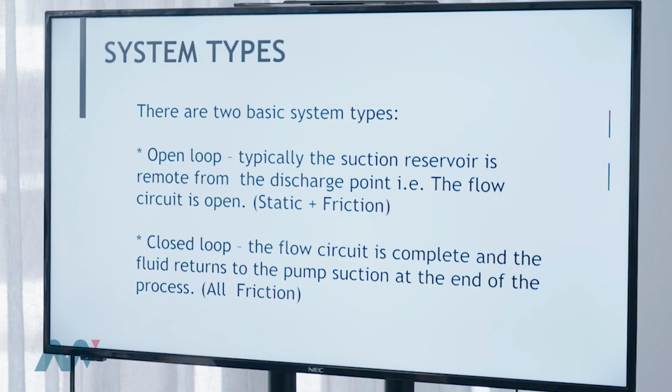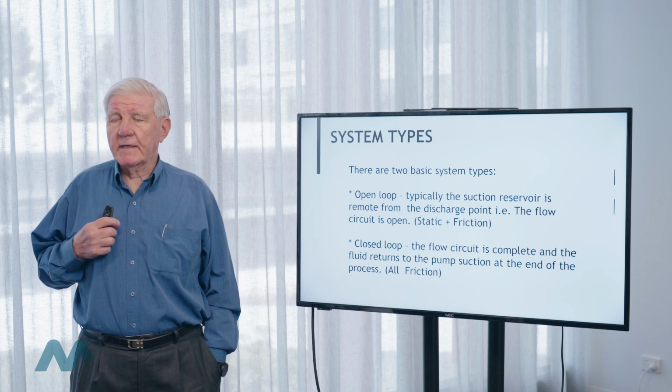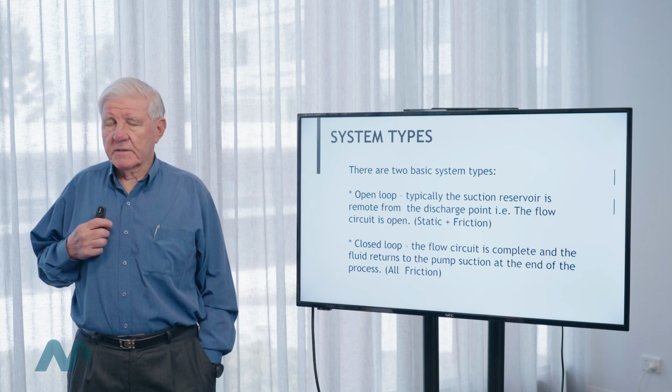If we look at systems, there are two basic types. There's an open loop system where the suction pickup point is different from the discharge point. And in such a system, we've got both static head and we've got friction losses.